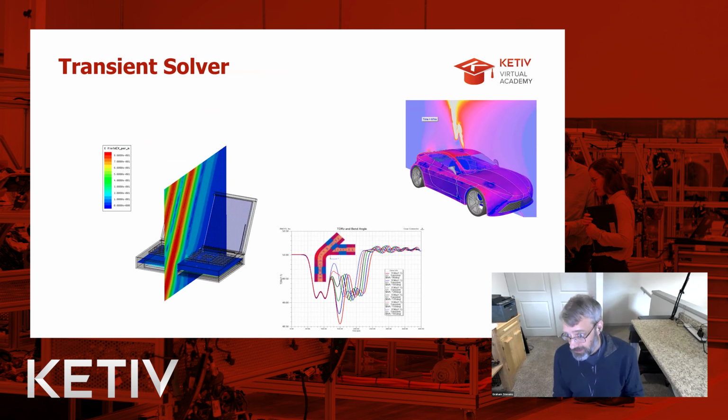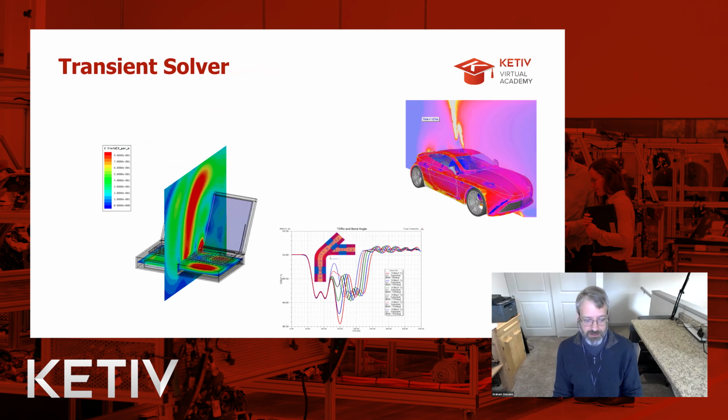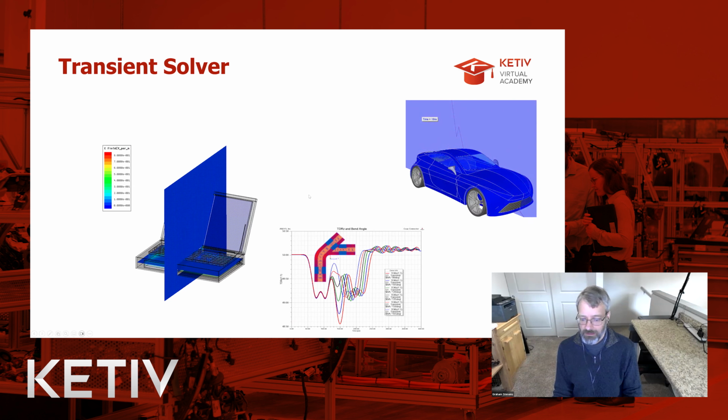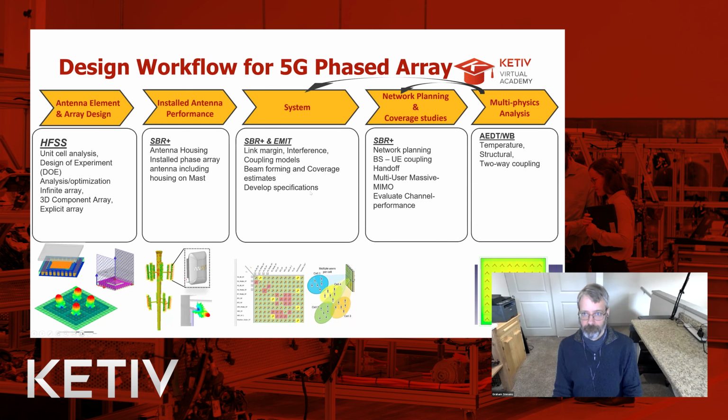And then HFSS itself also has a transient solver built in it as well, where you can do TDR analyses, etc., to get a sense of what's happening for transient analyses. So we can do the impact of lightning, we can do TDR analyses, etc., at the transient in the time scale.